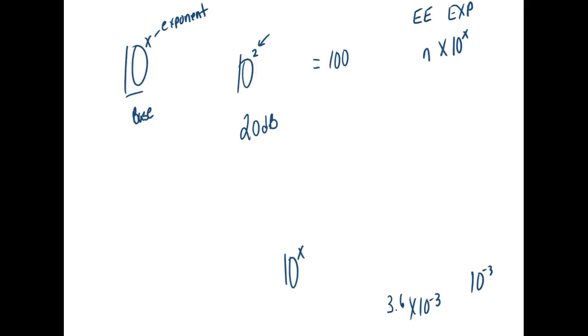So dB is a form of, like we use milli and micro. It's not a unit. It's not volts. It's not amps. It's just a way we can represent very large and very small numbers, right? So if I had 39.6 dB, the actual number would be 10 raised to the 3.96 power. Because dB is real nice: all I have to do is shift the decimal point. Right? You understand that? We shift it to the right when we multiply by 10. We shift it to the left when we divide by 10.